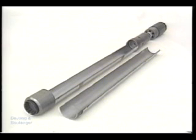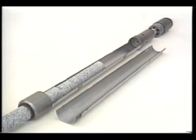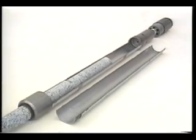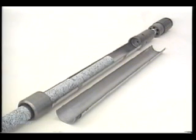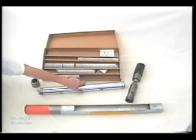As the core barrel is rotated and lowered, the core bit cuts an annular section out of the soil or rock. This section, called the core, moves up into the inner barrel where it is protected from potential erosion by the circulating fluid. Once the inside of the core barrel is full, drilling is stopped and the core barrel is removed from the hole. By disassembling the core barrel, a continuous sample of the soil or rock is recovered.